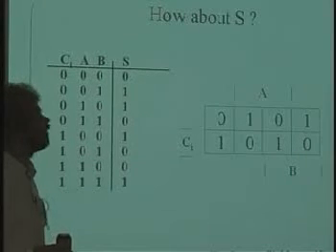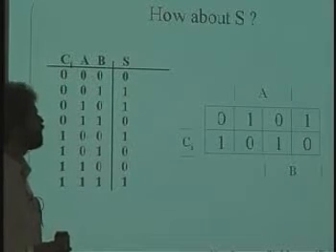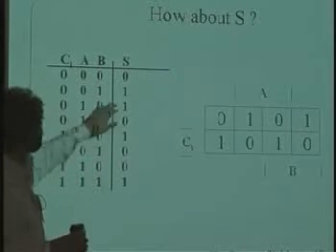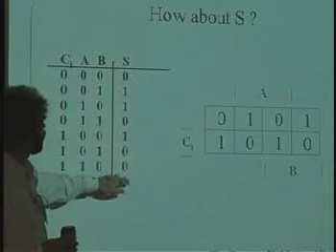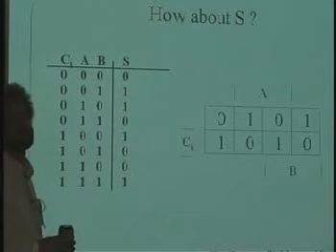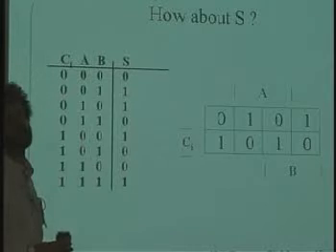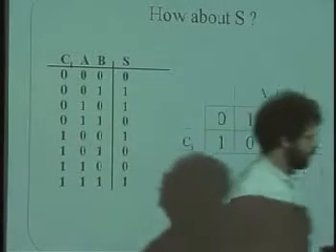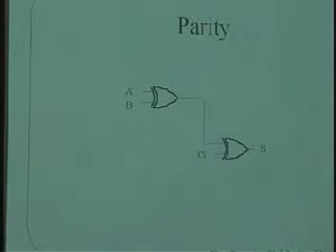So I can't make a sum of products form that's any more simple than having 4 terms, which we saw at the very start, which take into account the individual rows where S is 1. Because this is basically saying, is the number of ones in the input odd? That is what S is. And so it's exactly the parity function. Alrighty. So parity, however, does not mean that you can't build a circuit to simplify things anyway.